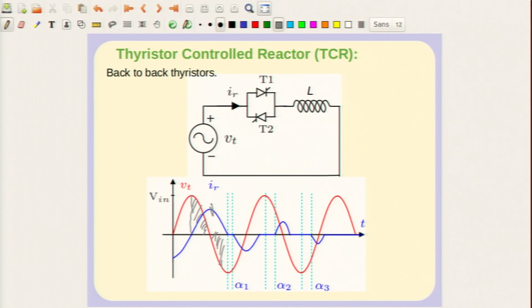It reaches a peak here and the voltage starts decreasing. If you integrate now, the current is going to drop, because when the voltage becomes negative, the integral of V dt implies a decrease in the current. So, this is if you delay the firing by 90 degrees.